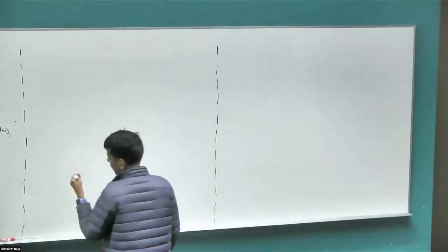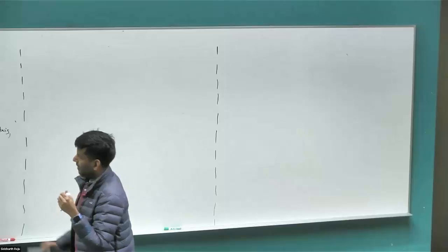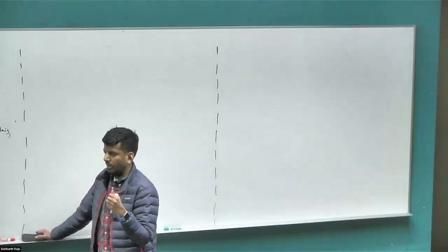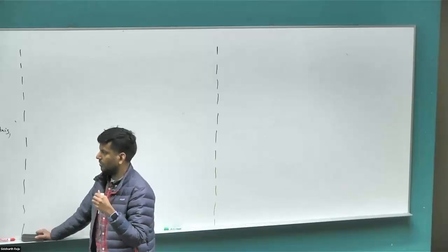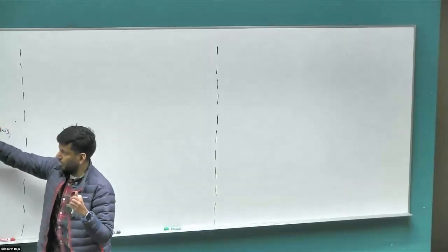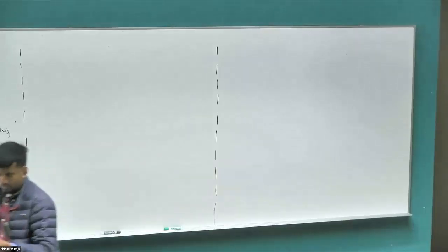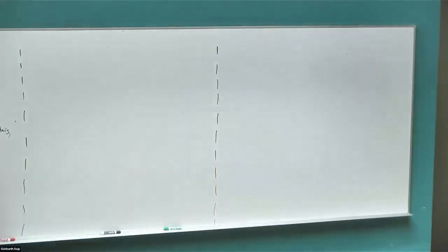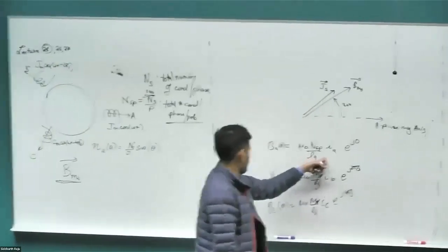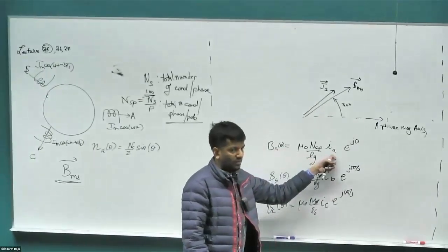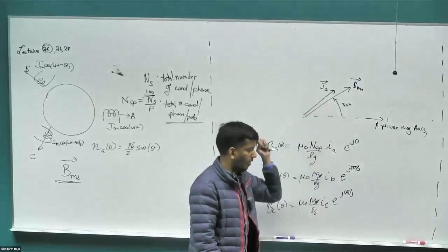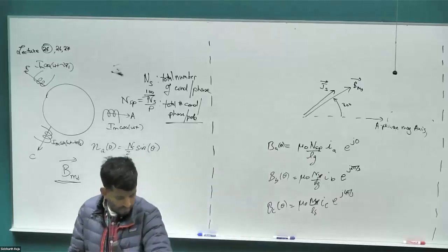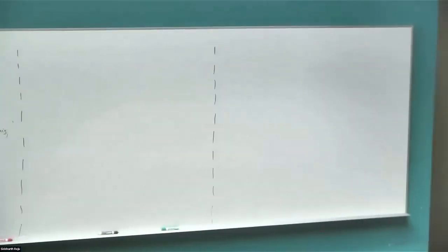So this is quite useful because going forward, you don't need to think about it every time I ask you where the current space vector is going to be at its maximum. You don't have to visualize what the current values are going to be and try to figure out where the current space vector is going to be. If I tell you where the B_MS space vector is, the relationship between B_MS and the current is just a straight constant scaling. So B is just related directly to I. If the current space vector moves somewhere, the B_MS space vector is going to move along with it. Or if the B_MS moves, current will move along with it. Right? So this is where those two space vectors that we draw here are.